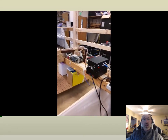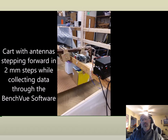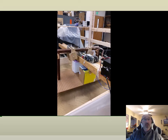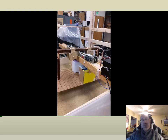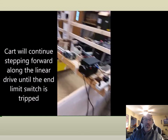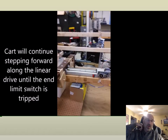So we come back over to our actual linear drive here. You can hear that clicking. Moving in 1 millimeter, 2 millimeter increments all the way across this while collecting the data and sending it to the BenchView software, our data acquisition software. As I mentioned earlier, this is a very slow but very accurate process. The reason we're moving so slow and in such small increments is that vibrations and movement of the antennas will affect our data. So we go slow, stop, send the data, acquire our data, click our trigger switch, go forward again, and so on, until we get all the way to the end here.